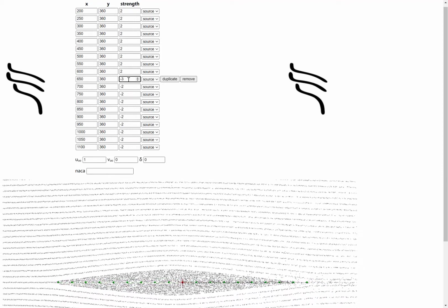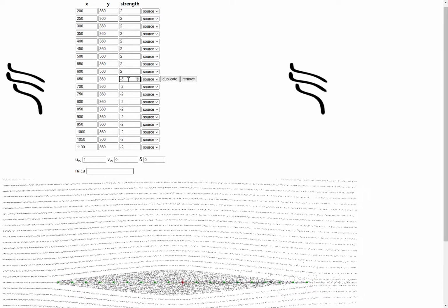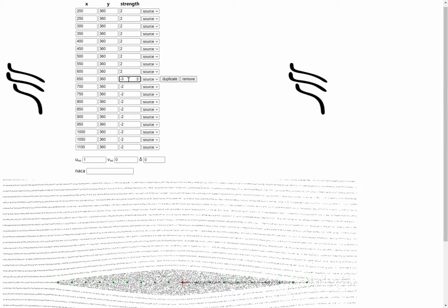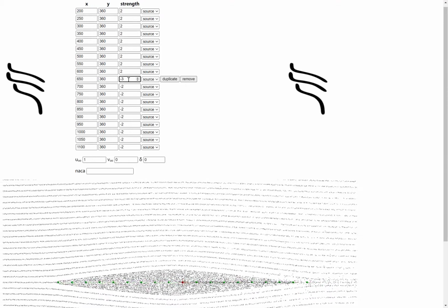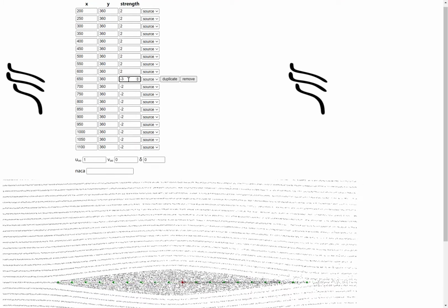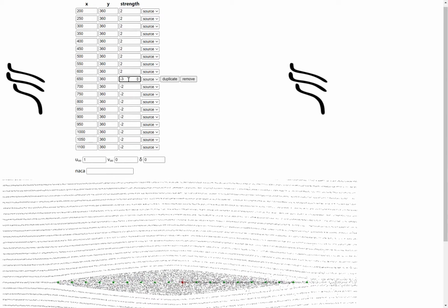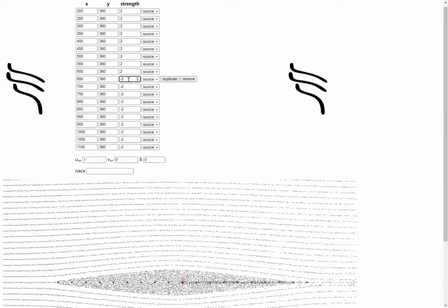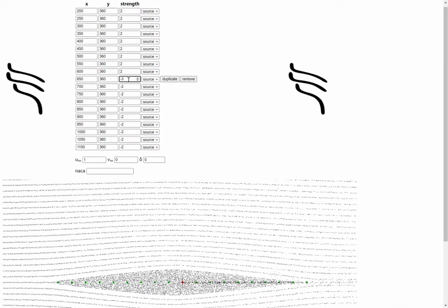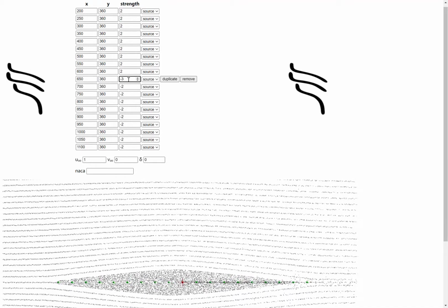So if you want a total of 0 mass flux, which is what should happen if you have a physical airfoil, the strengths should add up to 0. That's the only way to make the flow field a physical flow field around an actual airfoil. It's a very good idea to try, but just doing this would make it non-physical.